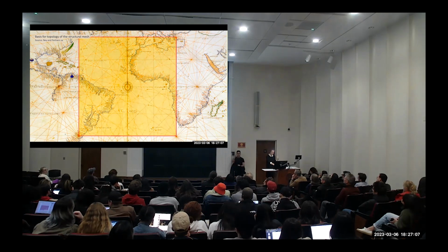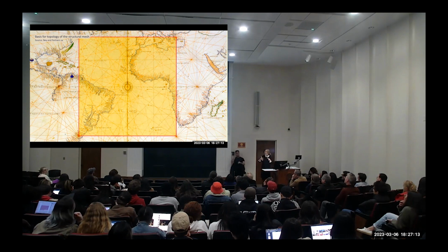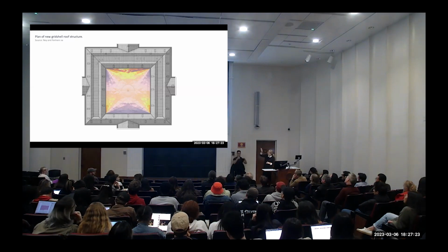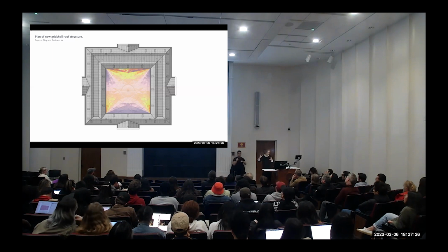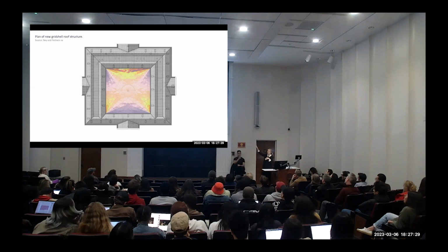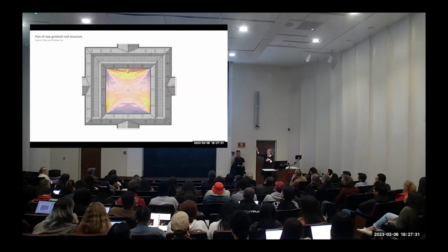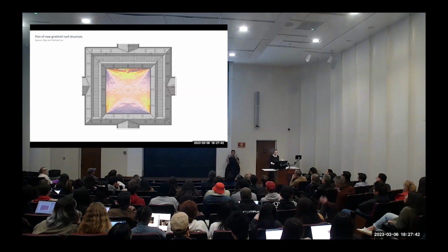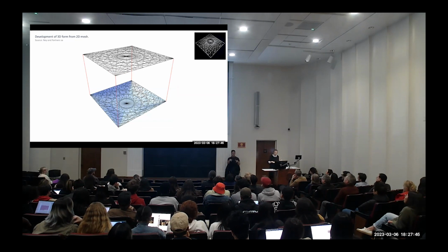So we extracted that pattern and thought it would be interesting if we, for the roof, create some kind of steel grid shell with a transparent glass roof that has this pattern in it. So we extracted it and imagined it in plan view on top of the building like this. Of course, as we've been talking today in the studio, the courtyard measures about 90 by 90 feet. You cannot span that with beams, that's too large a distance. So we could not make this a planar structure, or we would have to design it very deep. So we imagined how could this be designed as a kind of cupola.